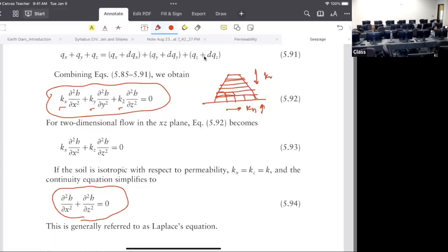That's a major theoretical difference on expansive soil. That's a completely different view in the mechanistic principle. So the anisotropy for the expansive soil is different in the upper layer, in the active zone. Below the active zone, again, you have the horizontal anisotropy. You get my point?